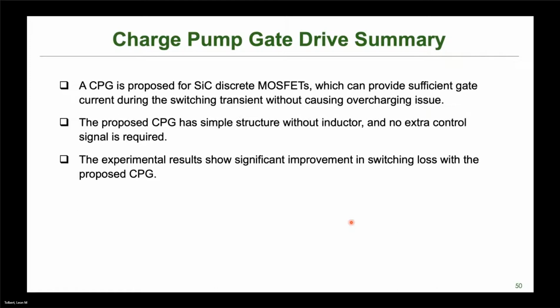So yes, I do think if you want to do soft switching, you can, and I think you have to with things like GaN. With silicon carbide, we haven't had to, and we have not explored really doing soft switching to a large degree with silicon carbide. That may be something that some folks could look at to see if that gives you some gains without incurring too much additional complexity or devices. Okay, thanks.